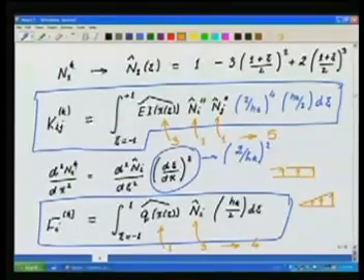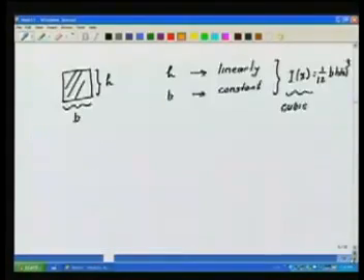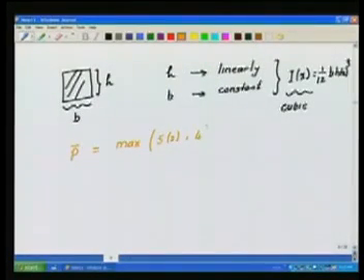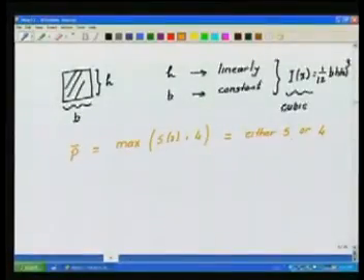So, let me write here within bracket 2 in case my EI is constant. Okay. So, my integrand p bar, if you remember, will be equal to max of 2 or 4. So, this is equal to either 5 or 4. Okay. With the understanding that it is 5 when I have a tapered beam and it is 4 when I have a beam with a constant cross section.